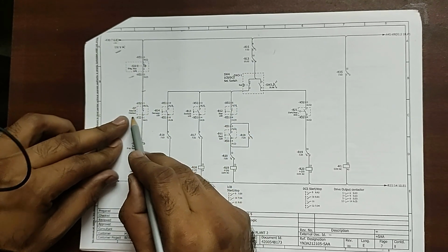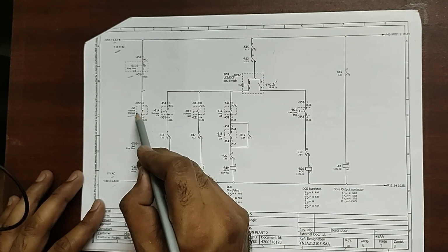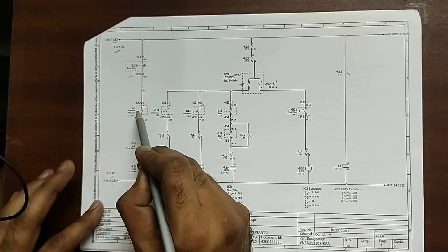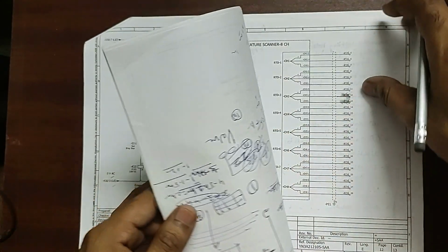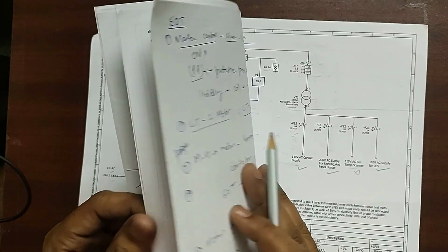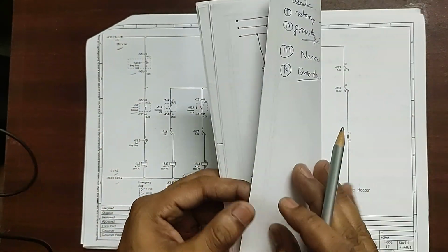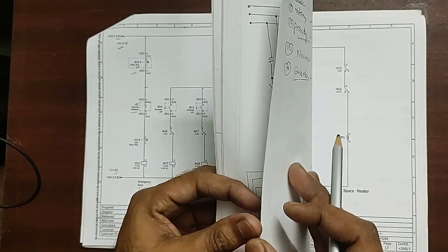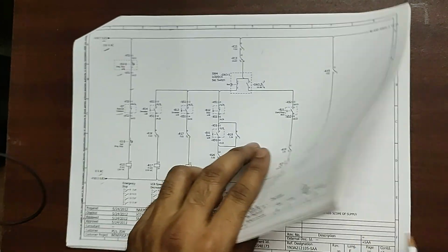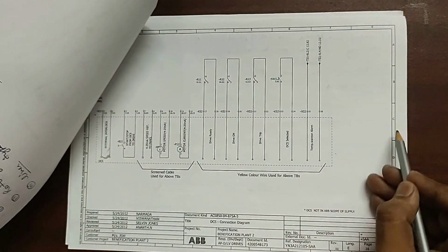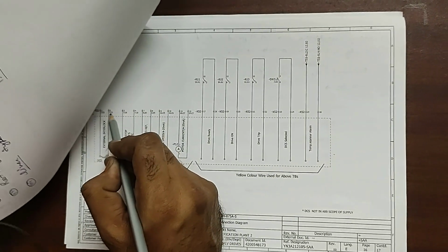And again, this is external interlock. If you need any external interlock, you can put it here. If not, you can just put a loop. That is X52 1 and 2. Now what is X52? Again, we will better check it because this is the most important piece. And page number 16 C1. Here it is written 16.C1. So this is page number 16. This is C and this is 1. C, external interlock. You can just put a loop here if it is not required.